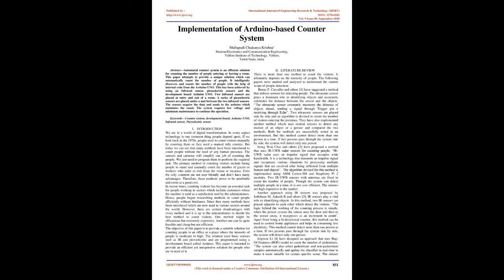This has been achieved by using an infrared sensor, piezoelectric sensors, and the development board Arduino UNO. Two infrared sensors are placed at entry and exit of a room. A series of piezoelectric sensors are placed under a mat between the two infrared sensors. The sensors acquire the data and send it to the Arduino, which maintains the count. The system requires low voltage and minimum maintenance to continue the operation.